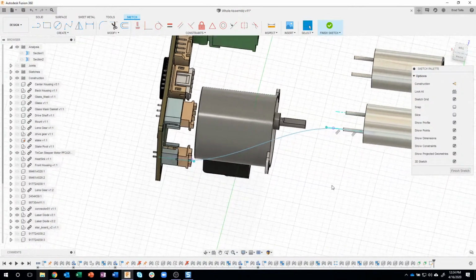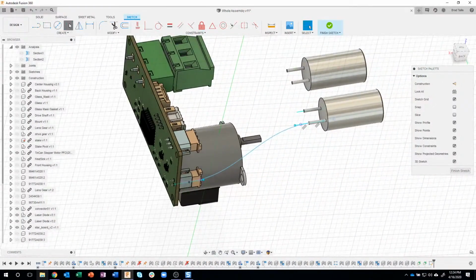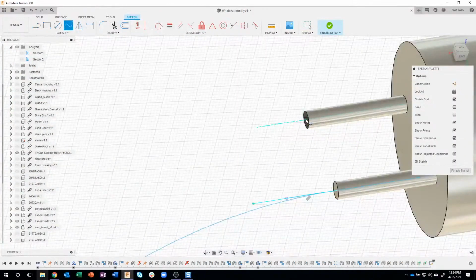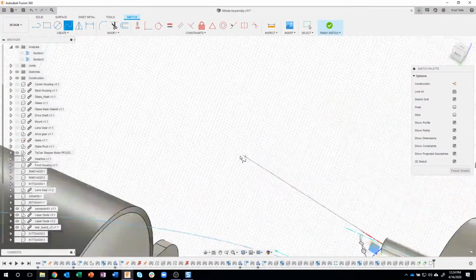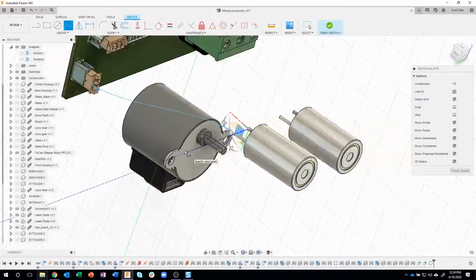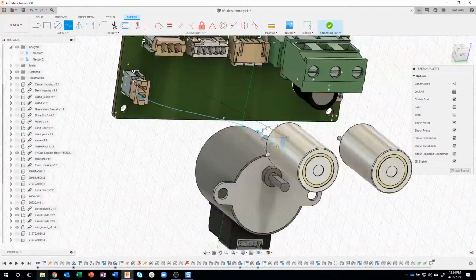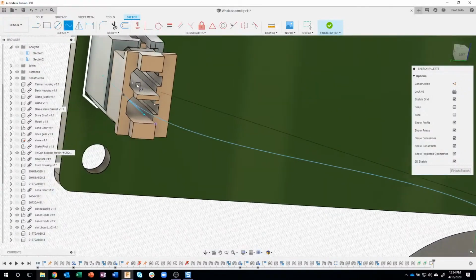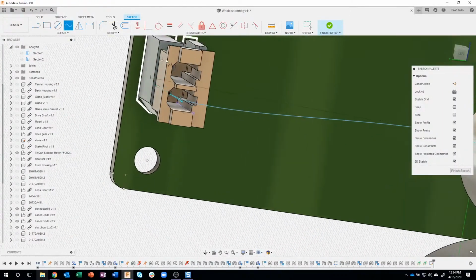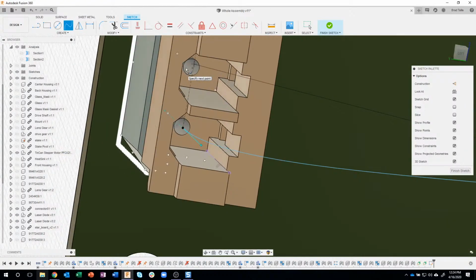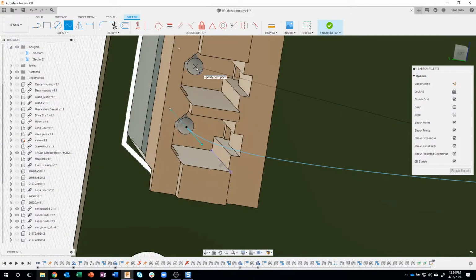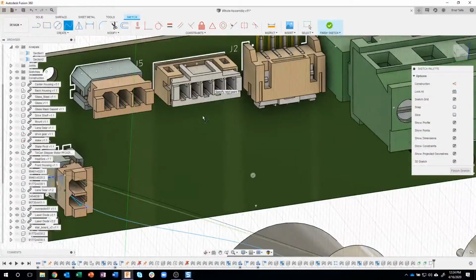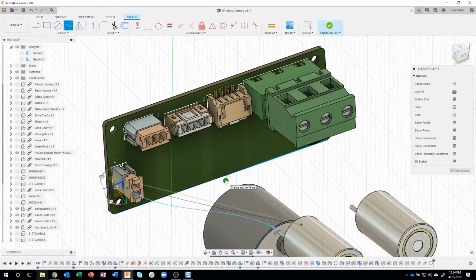I'm going to do the exact same thing, a little bit faster. I'll say spline, zoom up, grab that little box right there, rotate around a little bit, and zoom up on this pin, the upper pin. I can rotate so I can see it, and I'm going to move until I see that box up here. I'll click, and that's basically grabbing the center point of this little pin that's inside there. Right now it's a straight line. I'll say OK.